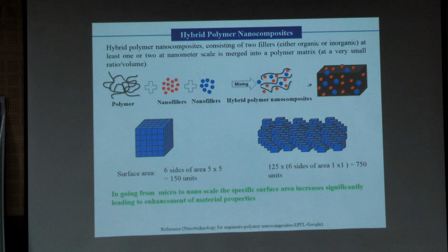So then this comes into the picture, the surface area. So if you take the same microparticle, you are making it into a number of particles of nano size, then the overall surface area is increasing. So because of the increase in surface area, some of the properties may be improved. That means the load carrying capacity may be improved.